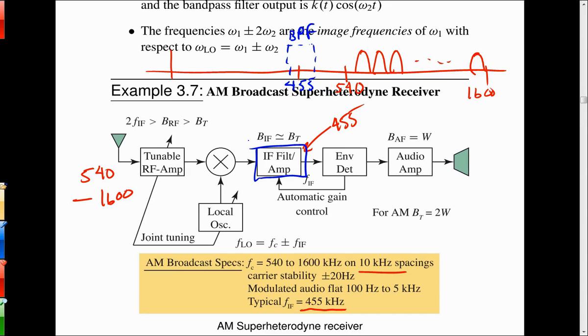So now we'd like to bring everything through that common frequency by making it pass through that common frequency using the local oscillator that comes into the mixer, the multiplier. And we know that multiplying a cosine times a cosine, and we think of a carrier wave as being cosine with some message on it.